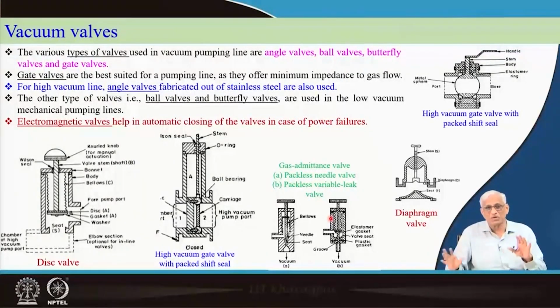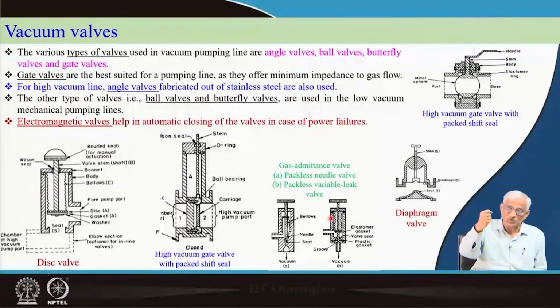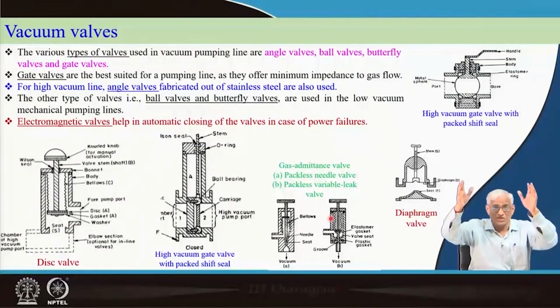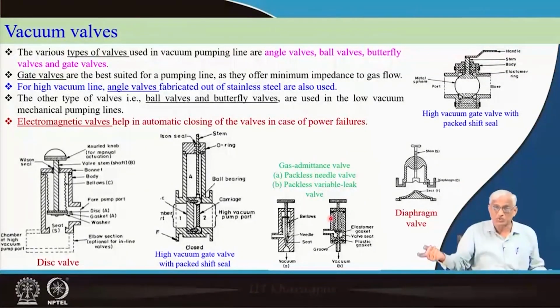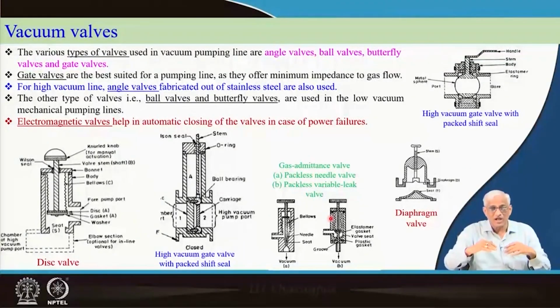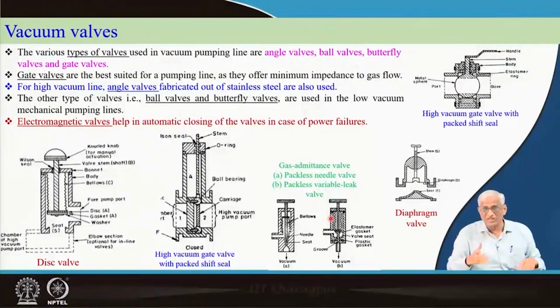When the diffusion pump and rotary pump together have created good vacuum, then you open the main isolation valve, assuming by that time the top vacuum system is not leaky. So, whatever vacuum has been created at 10 power minus 2 torr by the roughing line is retained. Now, when you open it, 10 power minus 6 torr is instantly connected, and to make a good conductance you make a gate valve there or cold trap, all these things we have seen, these are all components.